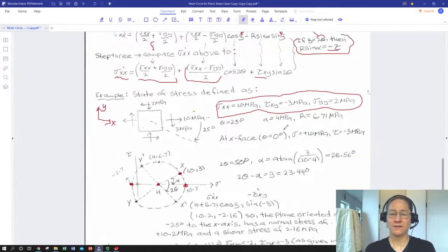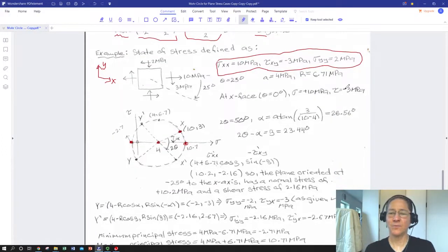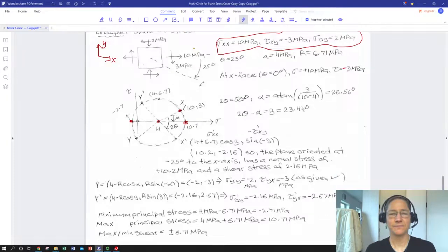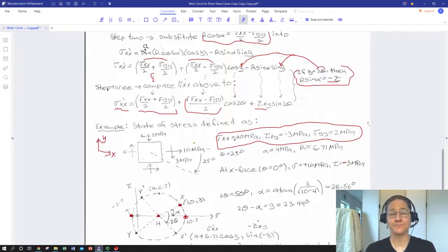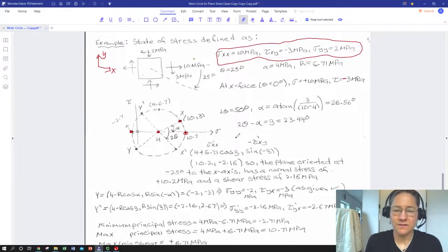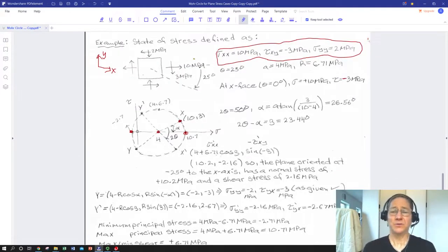we're plotting opposite with tau in this case. And that's another point that came out of this derivation. We're going to relate alpha and tau, or theta and tau. We're going to flip tau for this convention. So again, it's another convention to remember, but that's why 0 looks like a positive rotation on the Mohr circle from our principal direction.